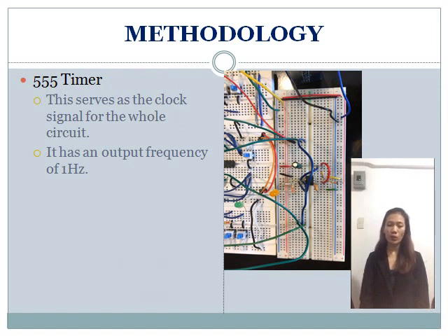First of all, we made our own clock signal using a 555 timer. We input a 10 microfarad and 100 nanofarad capacitor together with 5.6 kiloohm and 68 kiloohm resistors in order for us to attain 1 kilohertz of output frequency.